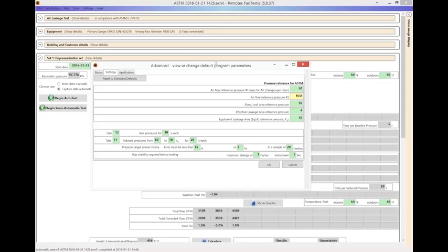And the other one is, I don't know whether you want to go into this right now, but there's a series of steps that you can follow that will allow you to check out each fan and its pressure circuit and its response to test speed before you start the test. So do you want to talk about that later? I don't have a slide for it, but if you want to go ahead and just, while you're on the line, just go ahead and talk about it.